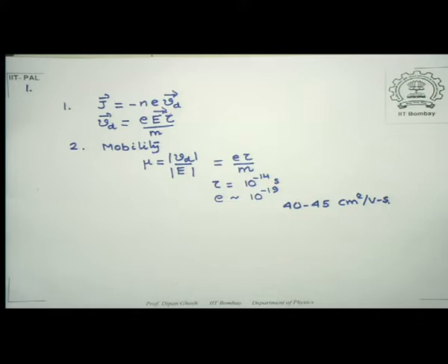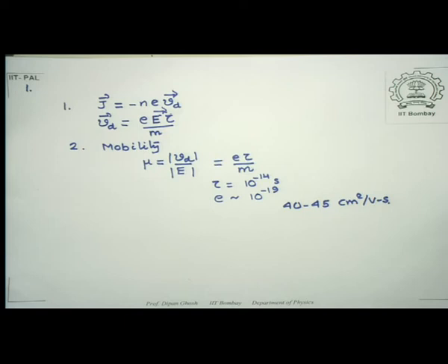We said that this is low compared to the mobility of the charge carriers, for instance, in case of semiconductors, and that is primarily because there being too many charge carriers in case of the metals, the frequency of collision is a lot more, and as a result the mobility is affected, the drift velocity is small. And so this quantity in case of semiconductors is somewhat large. In fact, we made a statement that large mobility is required for semiconductor devices to function smoothly.